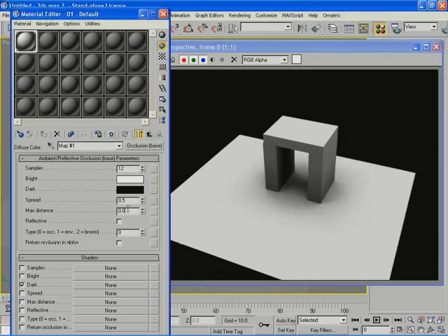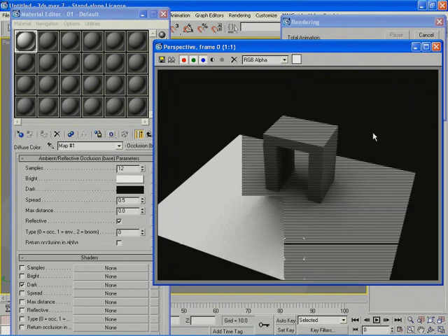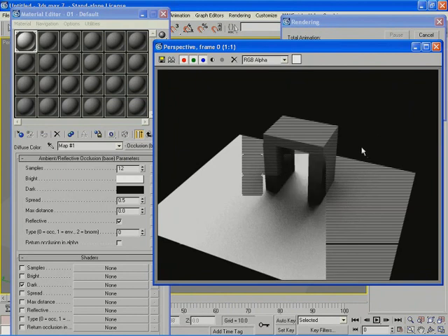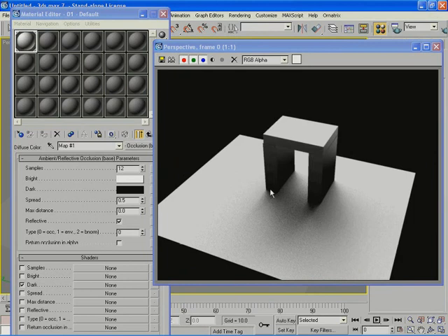Now, here I have reflective. So if I activate it, I'm going to have the rays bounce up and down from these surfaces until I get a sharper or actually a darker effect, which is not always useful. But here I have different types of reflection. So I have reflective set to occlusion first of all, and we get much more darkening whenever you use it.